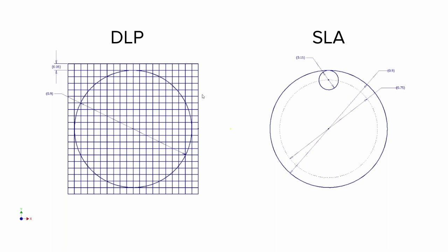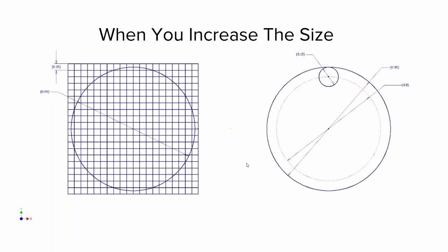So what really happens when you vary the tolerance? Remember it took about 50 microns or so to change a fit over to the next one, so a transition to an interference, for example. So we'll just increase that size by 50 microns, and you can see now we're at a 0.95 millimeter diameter peg, and now we're halfway between a pixel, and the printer has to then make a whole new set of decisions if it's going to turn a pixel on or off.